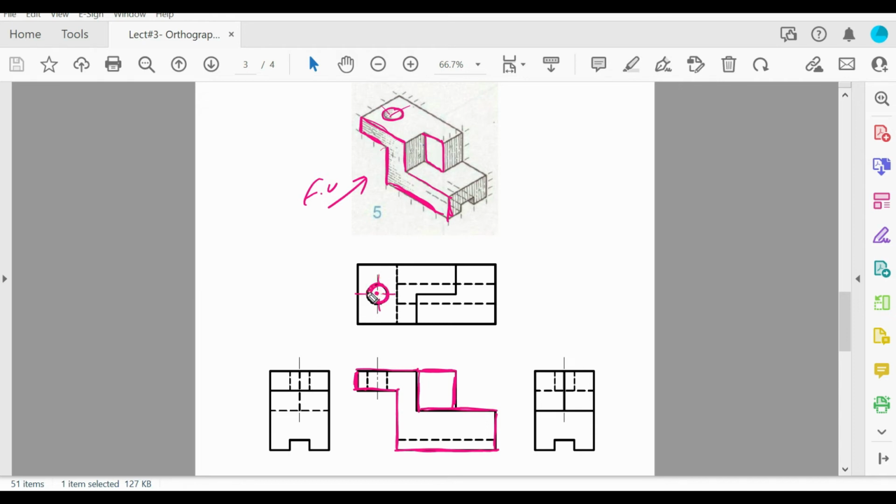In the top view, sorry, I'm talking about the front view, not the top view. In the front view, this is the location from here to here. This distance should be taken from the 3D view, and I will draw the axis here, then shift with distance equal to radius, and draw hidden lines, because this is a hidden cylinder here.